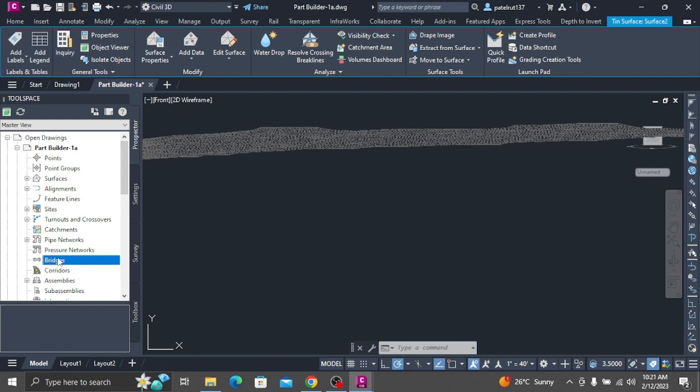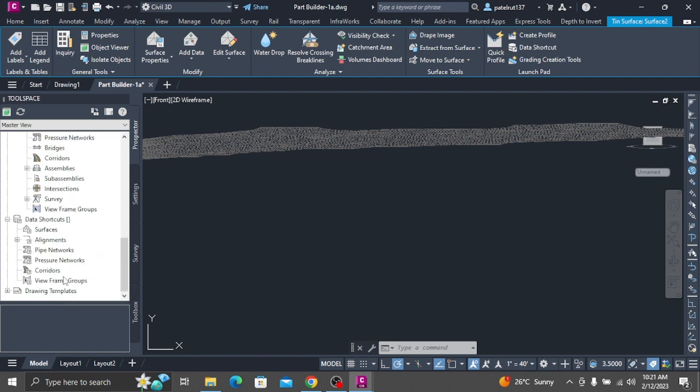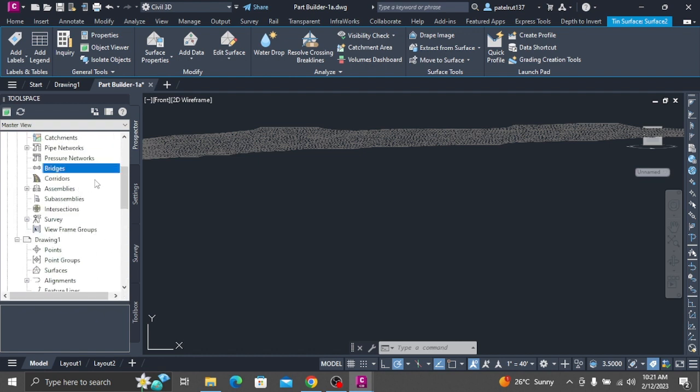Click View tab, Views panel SW Isometric. This 3D view is better suited for the next steps. Right-click Modifiers Add Extrusion. Click the outer rectangle. The Extrusion Modifier dialog box is displayed. Verify that type is set to blind. Enter 8 for distance and check the box next to flip. Click OK. An extrusion modifier is created for the outer rectangle.